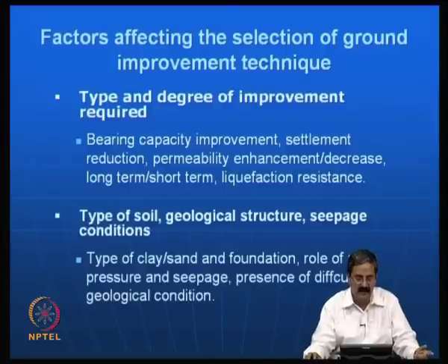In many projects, there is a significant effect of ground improvement techniques in terms of cost, sustainability, ease with which it can be done, and confidence to the profession. There are many issues here. Then the role of pore water pressure and seepage. I just mentioned the permeability enhancement or decrease. If you want higher pore pressures to be dissipated, if the water can go faster, the drainage is better. When the drainage is better, pore pressures are less. So, you provide a means of proper drainage.